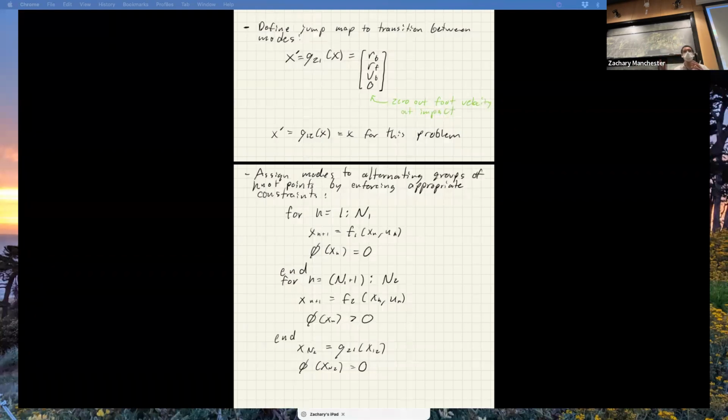What I can't do though is, if I have, say, a quadruped where I can have walk, trot, gallop, different gaits, the thing that you are pre-specifying here is basically the gait. So I can make the exact timing vary, but I can't change the ordering of the feet touchdown and liftoff. If I start with a gallop gait, that's what I'm going to get.